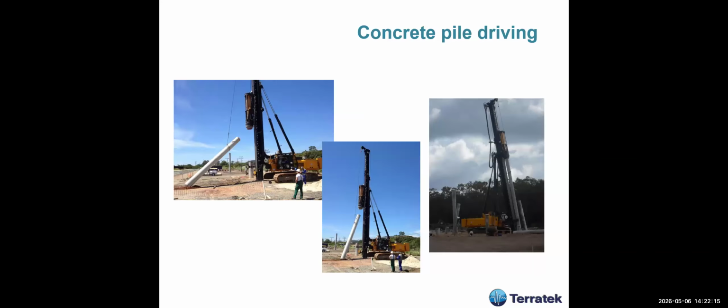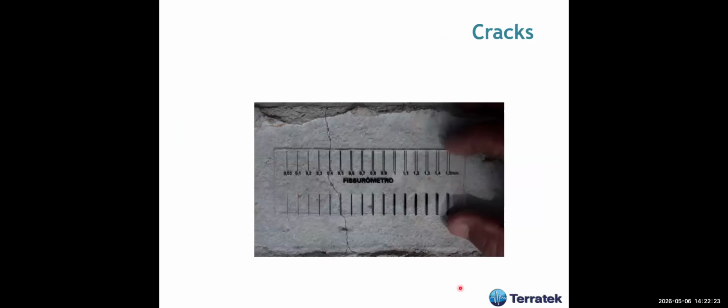Okay, this is handling concrete piles very carefully in another project which I've been involved in. This is the hammer. We're going to discuss this. And then what you have to do before you install a pile is quality control. Usually you have to look for cracks because these are very common. During transport, during handling, you may crack the piles if you don't do it properly.